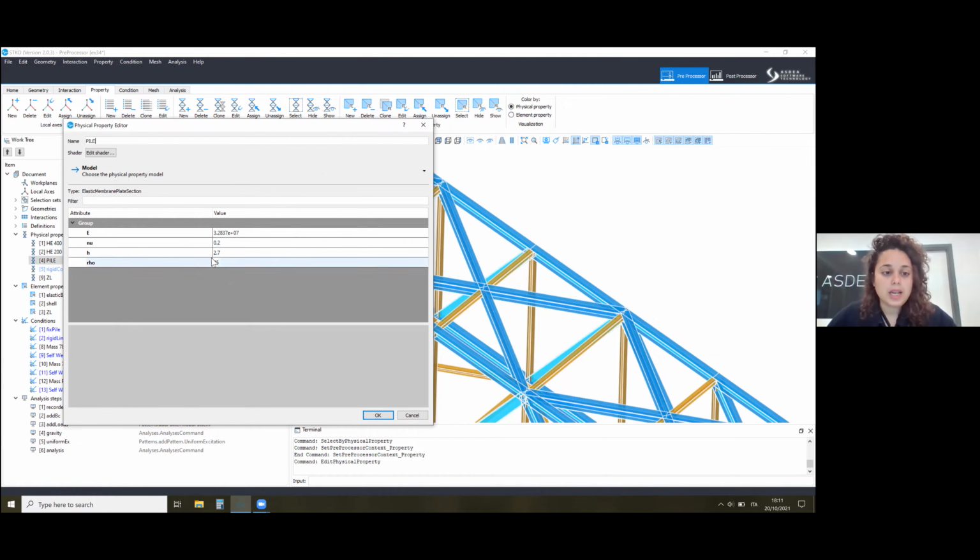In this case, you can assign either a density if you don't want to use the mass, or you can just apply a mass. I did both, but here it should have been like this. And then you have to assign a stiffness, a Poisson coefficient, and a thickness. In this case, our model is in meters and kilonewton meters, just to make a change from the other examples I gave you, which were in Newton millimeters.